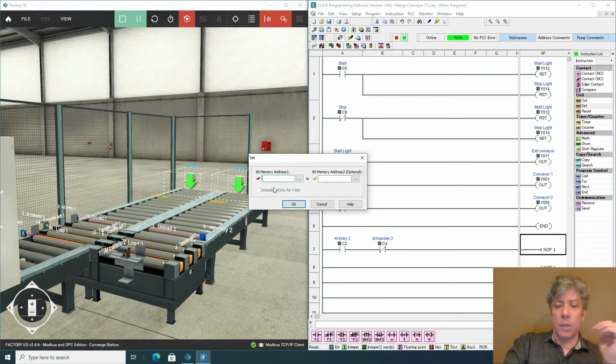Now if all I do is turn on the rollers, I've missed an opportunity because something important happened. A set of conditions was recognized that needs to be remembered. I recognized that I'm at the beginning of the sequence because I've got something at the end of conveyor 2 waiting to come onto the transfer conveyor, but there's nothing in the transfer conveyor. That's something worth remembering. So rather than just turning on the rollers, let me set a memory bit.